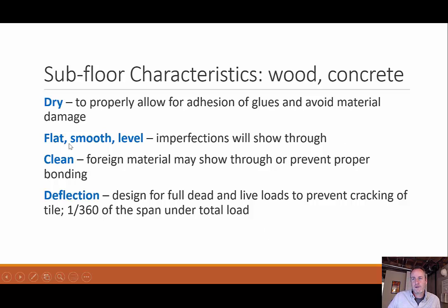Whether it's wood or concrete, we need it to be dry. We can't have a wet surface, because if we have moisture issues, then when we put down our adhesive or whatever else we're doing to attach these materials together, we won't get a good adhesion between our materials. We also need it to be flat, smooth, and level. So if I have flooring that is a little catawampus, sloped in a weird way, I may need, if it's concrete, a leveling compound. If it's wood, it may need to be sanded or whatever else, because these deformations, these characteristics will show through when we actually apply our floor.